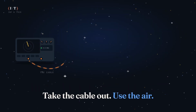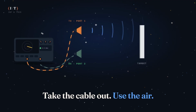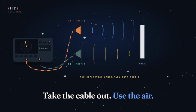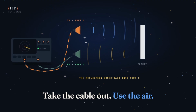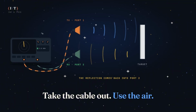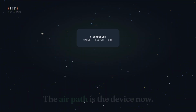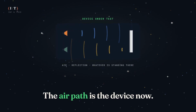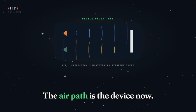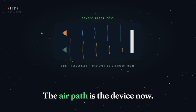Now, the build. Unscrew the cable. Put a horn antenna on port 1, another on port 2, and stand them side by side, pointing the same way. Port 1 transmits, port 2 listens. Put a metal plate a meter distance out. The device under test is now the room. The air, the plate, the reflection off it, that is what the instrument is measuring. Same instrument, same S21, only the device under test changed.